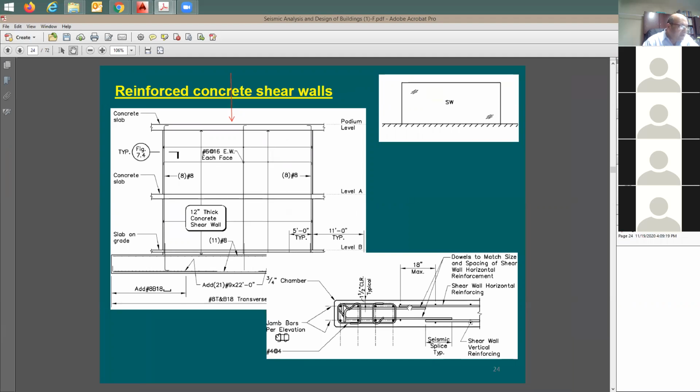And then you look at all of the bars, the vertical, because this is a section like this. You see this? A section looking down. So you look here at all the rebars. You count all the cross-section area of the rebars. You just add them up together and then use them in your equation. And you should be fine. This gives you the axial load capacity of the wall. And you're going to see it is really big compared to a column because the cross-section area is just extended, right?